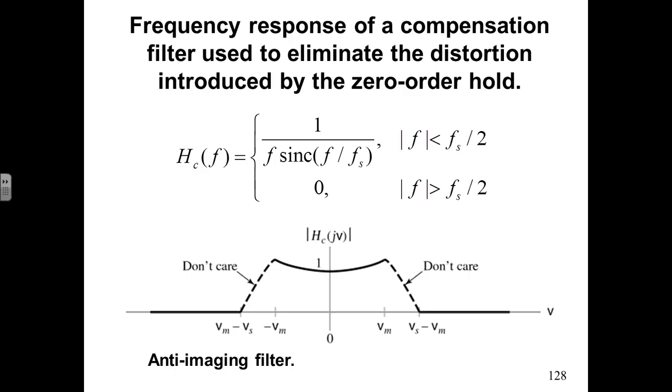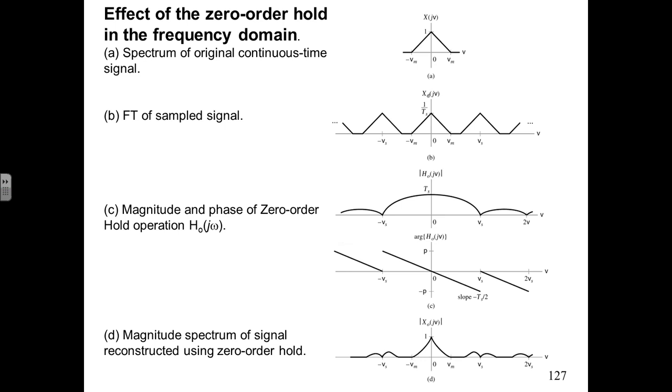What do we do about that? Well, if it's really critical, it's not uncommon for systems to try to compensate for this using another anti-imaging filter, either an additional analog filter or more likely some pre-processing done on the digital signal before it's put out, to effectively change it with this sort of inverse filter that reverses the effect of the distortion from the zero order hold filter.